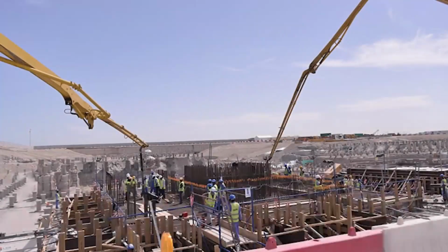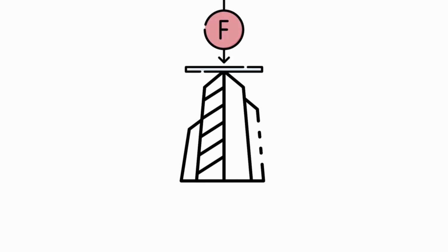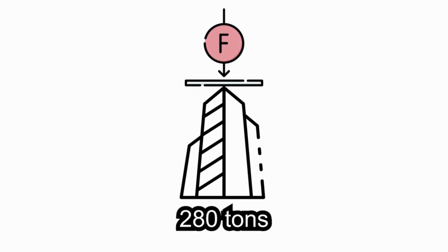As well as temporary windows, giant concrete plinths have been constructed across the site just to hold some temporary towers at the concrete height. Some temporary steel towers receive a load of 280 tons at one point to handle the force exerted on the walls and floors of the museum.